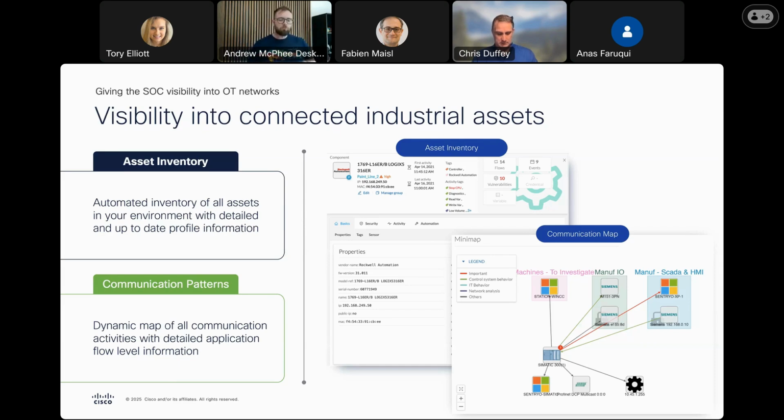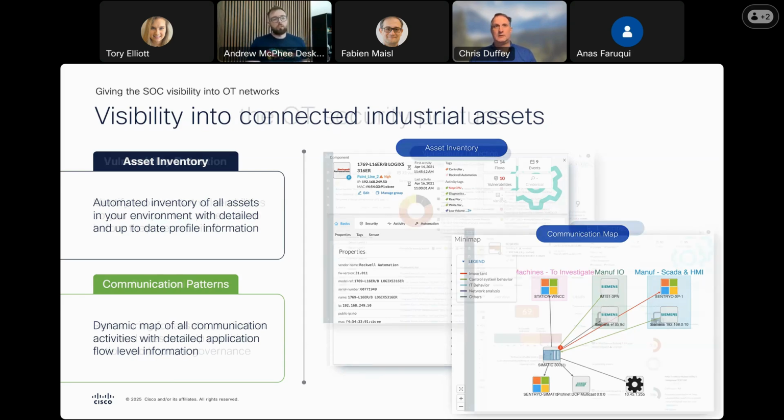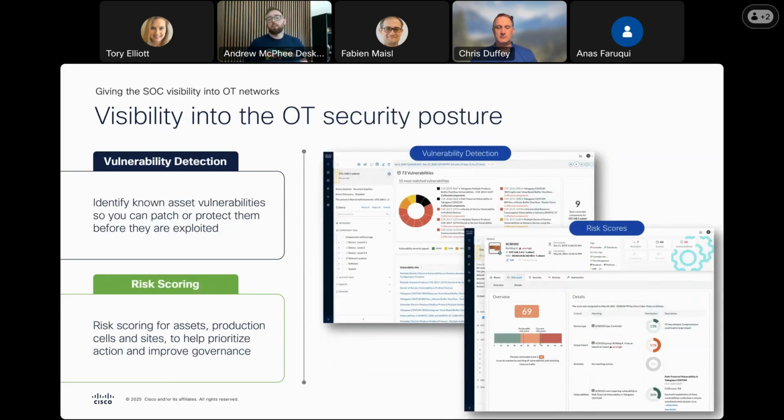And as part of those transactions that happen in an OT network on a daily basis, if someone opens up one of those vendor tools like a TIA Portal for Siemens or an RSLogix for Rockwell, we will see the interaction between those devices and be able to pull things like the firmware versions and the model numbers and basically the device properties that lets us know in detail what is this device. And when we get that detail of what's in that device, we can then tell you the risk that device has in the network.